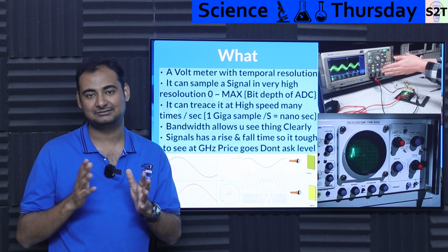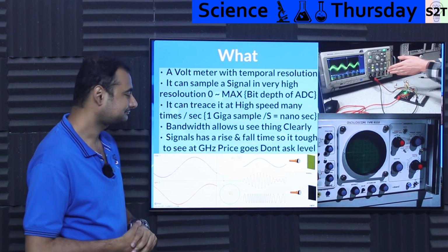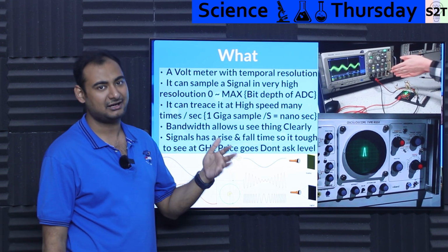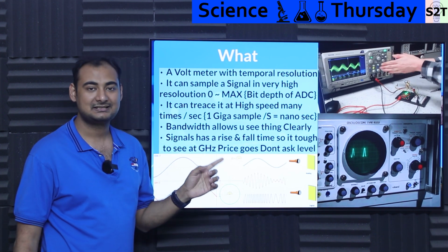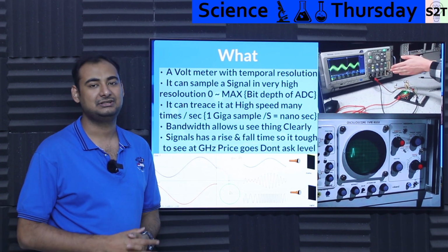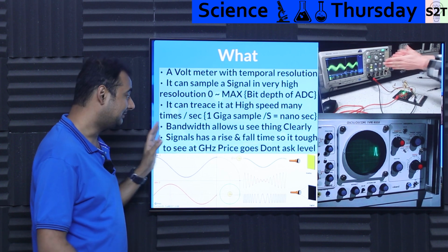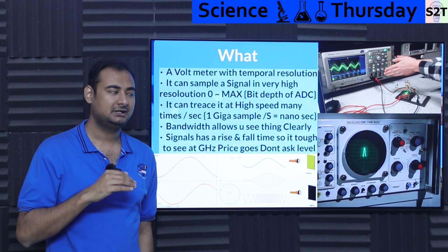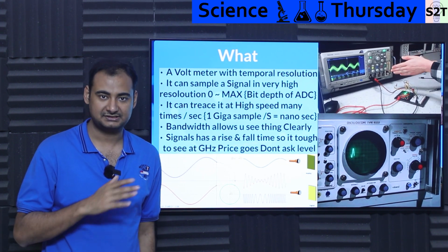You would need 44.1 kilohertz. So same way, they have to double the sample. Same here. Now here double, you need far more than that. So 1 gigasample does not mean, oh, I can give you 1 gigahertz of bandwidth. So bandwidth allows you to see clearly how the signal is rising. We say signal, like digital signal or processing signal, whatever have you.